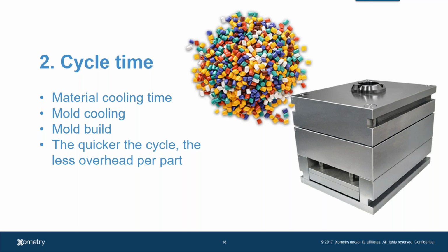You have stuff like mold cooling, right? So just a word of warning, if you have a mold built by us or outside, make sure it has water circuits in it, okay? It does change the cycle time of the part. It does change the appearance of your part. Mold cooling, essential.